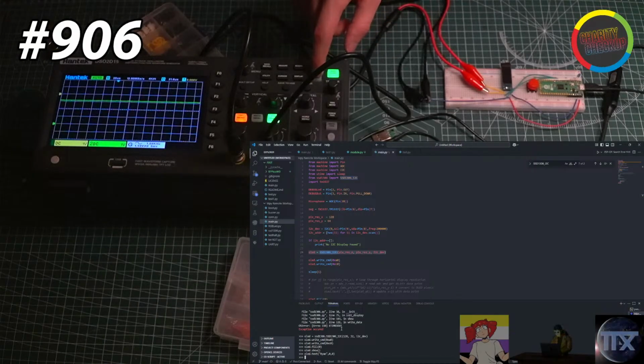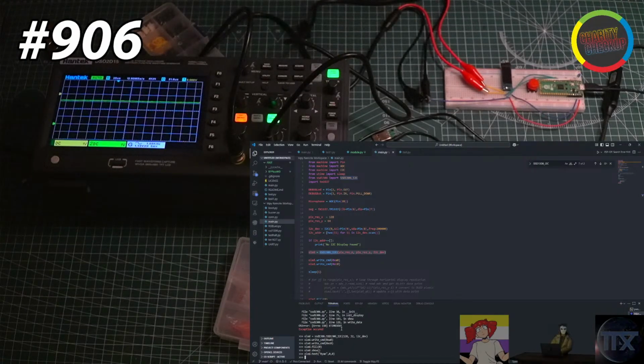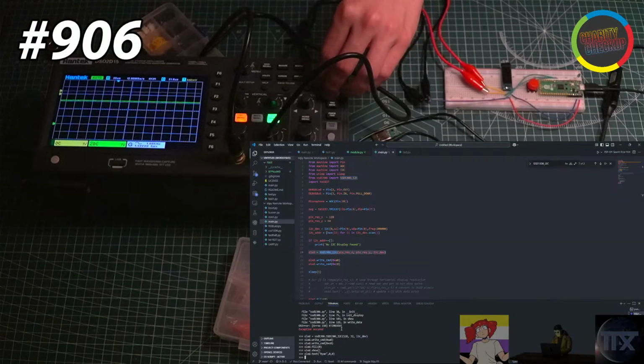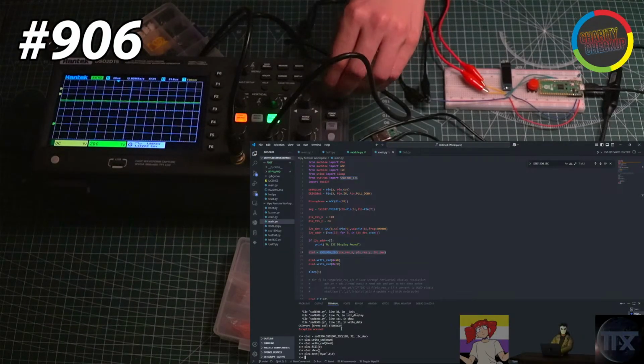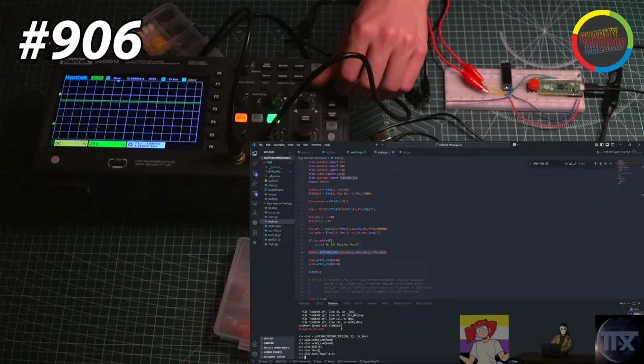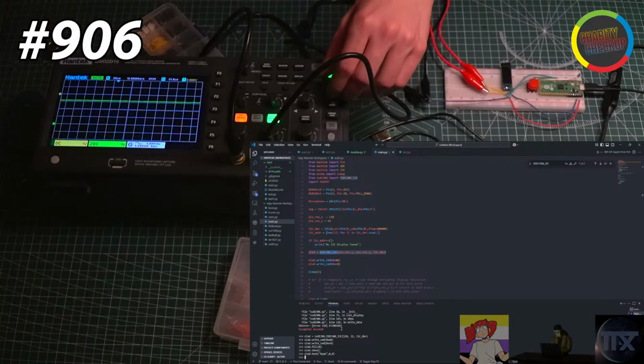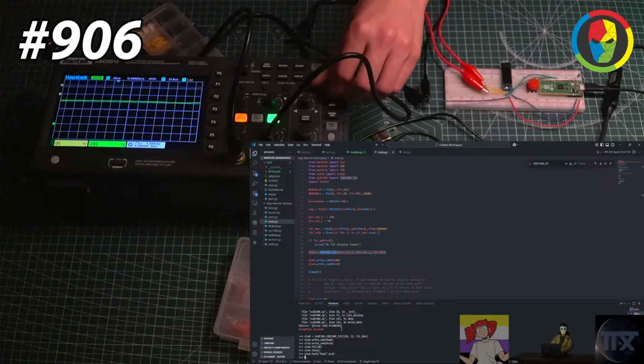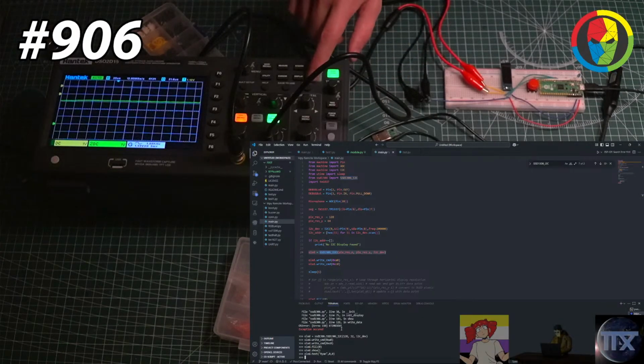Okay. Well, where's your trigger line at? Maybe between this and the clock, shouldn't it? It's on... hold on, I'm trying to read it backwards. It's on 0 volts right now. Well, that could be the problem. Let's put it at 1.2. There you go. Halfway in the center.